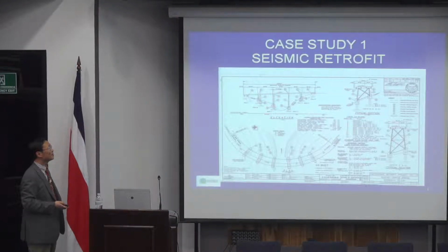design, in theory, you need to apply for all kinds of X direction, Y direction, and anything in between kind of situations. But that's typically for longitudinal, for straight bridges. For bridges of this nature, probably you need to apply load at different angles, just to see how the load may affect the structures.